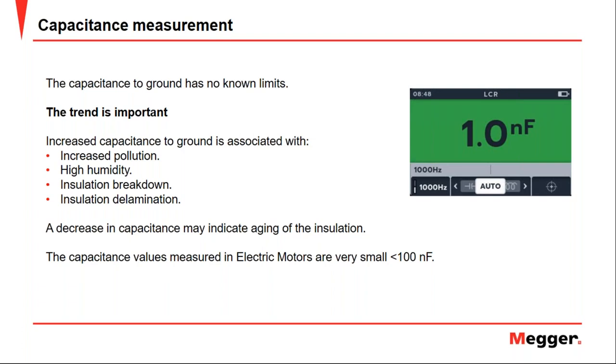Capacitance. As we said before, capacitance is useful, like inductance, only by trend. That is why we must take several measurements before carrying out any kind of analysis. Now, let's see what we can know with the capacitance test. We have here two scenarios.